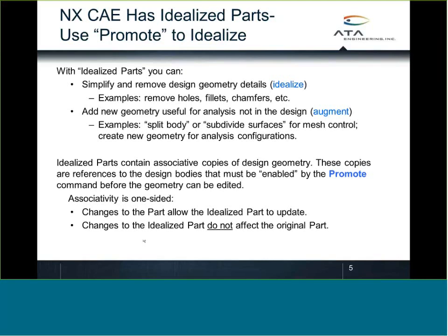When you think about this Idealized part, I want you to keep two things in your mind: idealize and augment. When I say idealize, what I mean is that you can do certain things to the geometry, such as remove holes, remove fillets, remove chamfers, things of those nature, defeaturing the geometry. And when I say augment, I'm talking about adding to the geometry in some way or modifying features such as splitting a body or a volume, subdividing surfaces, or creating entirely new geometry for the purposes of analysis, configurations, or